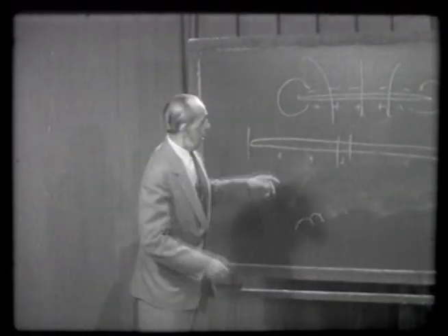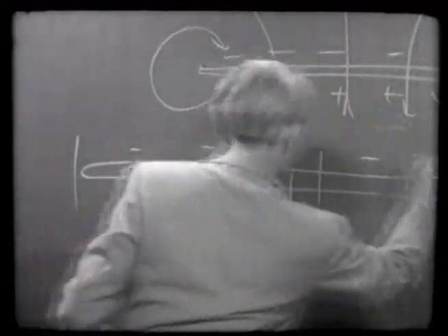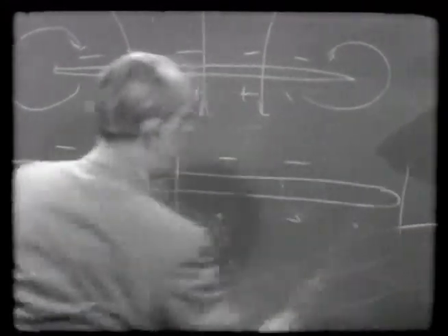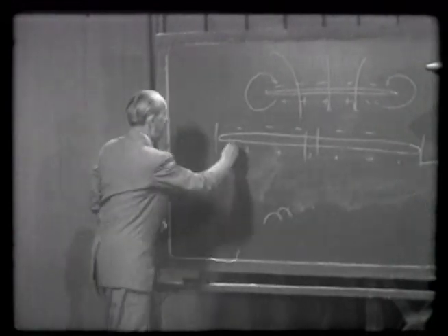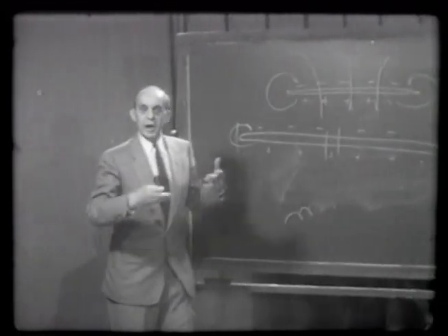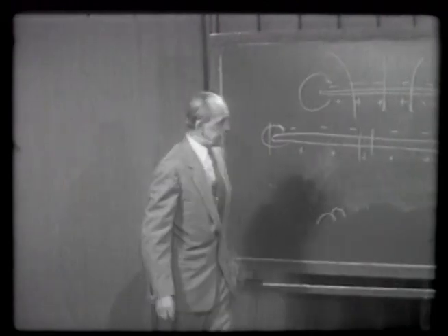And therefore, when this pressure differential from below to above is smaller, then also this rotation is smaller, and we get smaller tip vortices.